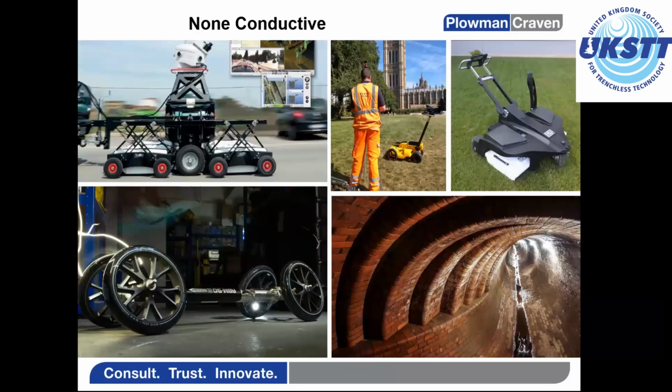These have dual head sensors integrating 250 megahertz and 700 megahertz antennas. It provides the largest dynamic range and depth penetration, but we are required to perform grids in line with the PAS 128 methodology. So that's M1 and M4. We collect and process said data dependent on the P suffix.